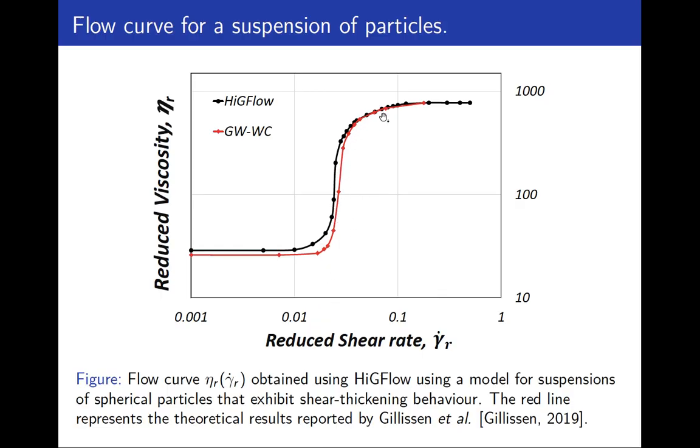And this increase in viscosity is actually happening very quickly, because here, for instance, this interval is really small, but you observe a really rapid increase of viscosity. This is a logarithmic scale, so you can see how the viscosity goes from 50 to, let's say, 800 in just this small interval of shear rate. So, as I said before, this is shear-thickening behavior.